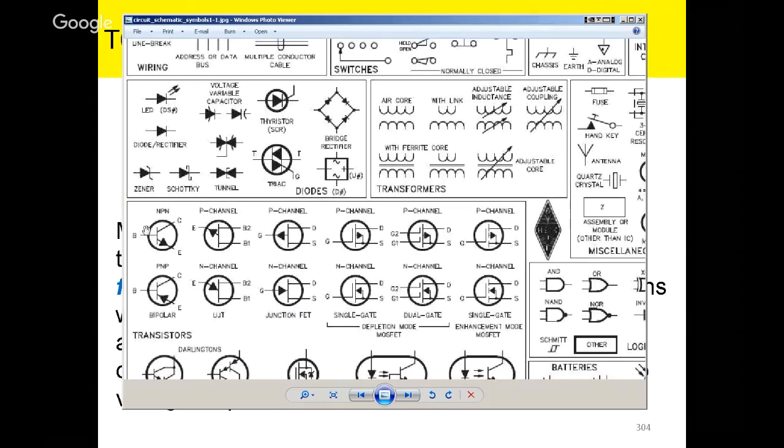In a standard transistor, you have a base, a collector, and an emitter. And this is an NPN, meaning your emitter is a negatively doped material, your collector is a negatively doped material, and your base is a positively doped material. Conversely, the PNP is a little bit different. And when you get into FET transistors, which is represented here, they're named differently. You have a drain, a source, and a gate. A gate functions pretty much like it says. It determines how the drain and source are going to function, amplify and control voltage.